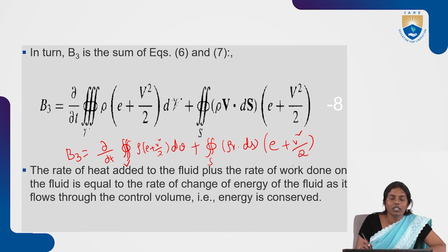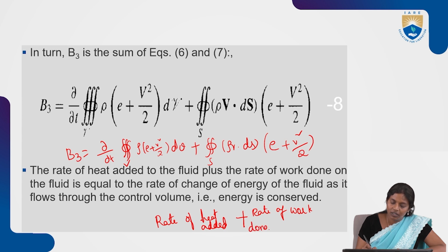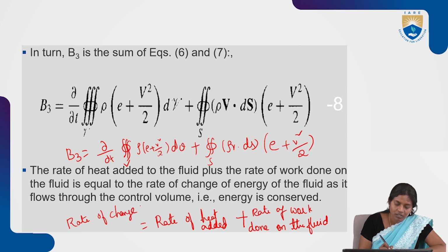If we consider the overall energy equation, the rate of heat added to the fluid plus the rate of work done on the fluid is equal to the rate of change of energy in the fluid as it flows through the control volume.